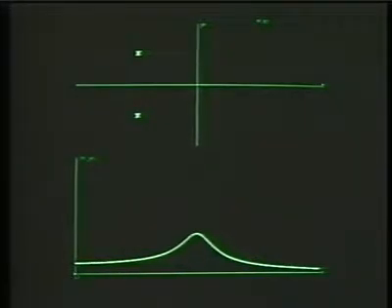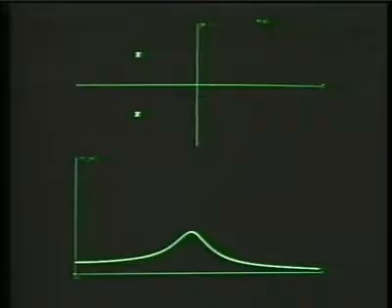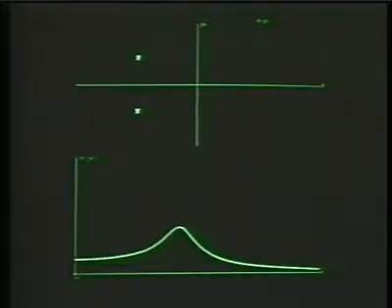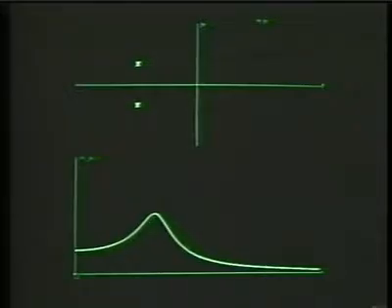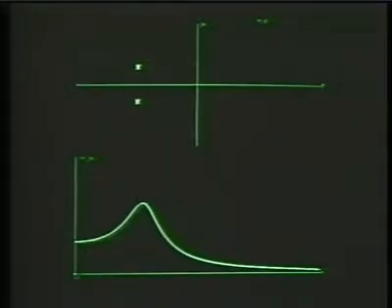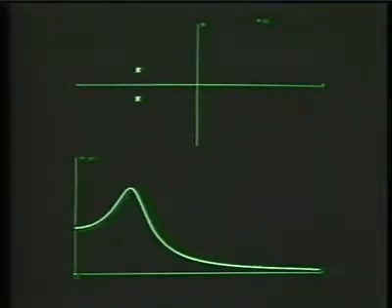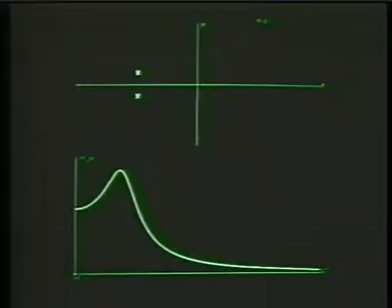Now we'll move the poles even closer to the real axis. The frequency location of the resonance will continue to shift toward lower frequencies. And also in the process, incidentally, the height of the resonant peak will increase because, of course, the lengths of the pole vectors are getting shorter. And so we see now the resonance shifting down toward lower and lower frequency.